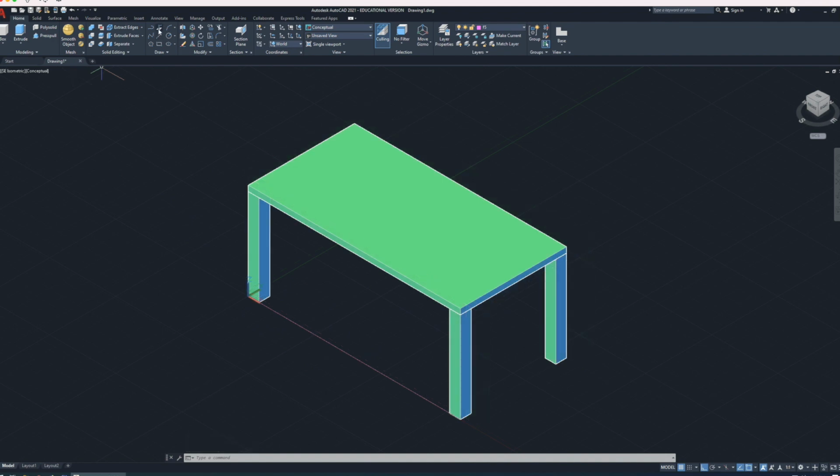I'm going to come up here and get the polyline tool, and I'm going to come down here and find the center of that line, and then I will come out 10 centimeters, and then I'm going to go up, make sure this goes straight up, make sure it's a dashed line, and I'm going to type the height of the shoulders above the floor, which is 123 centimeters, and then I'm going to go horizontally to the right, and